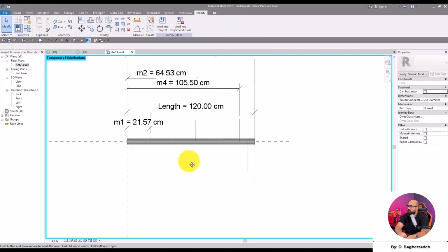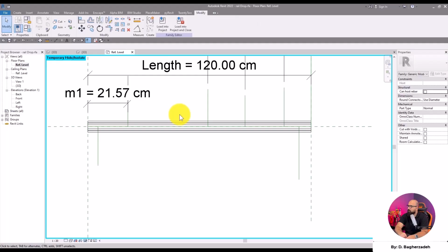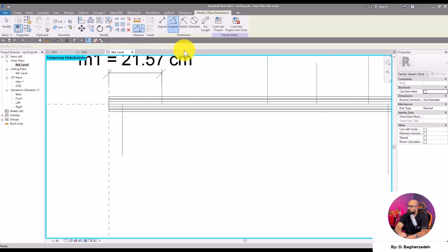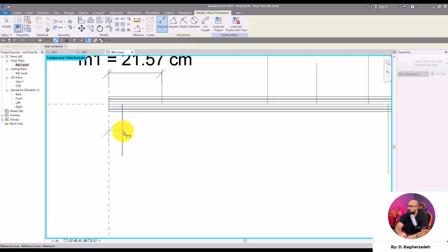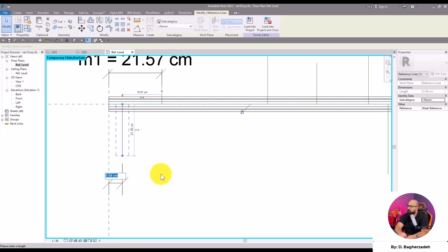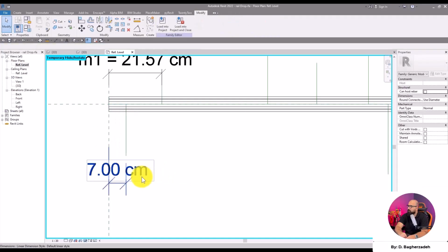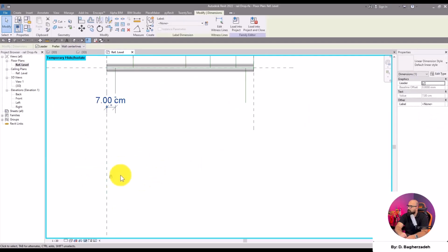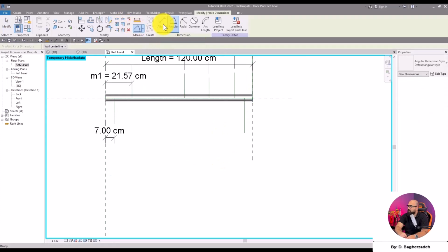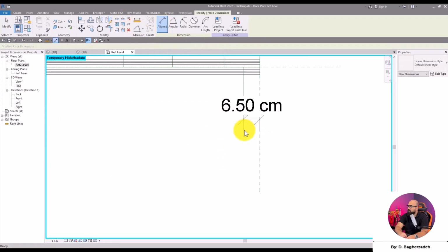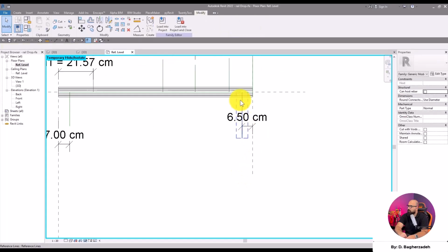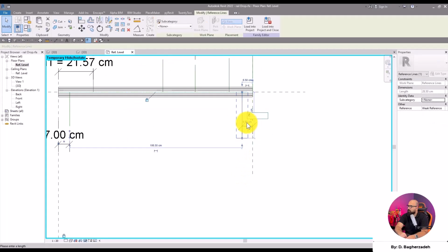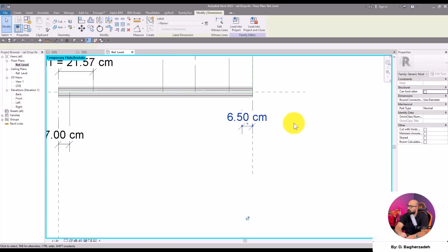Okay. Now guys, remember, the gap from the ceiling could or actually should change, but we need the same profile at the endpoints of our cable. More precisely, I'm going to go ahead and set a dimension here. Let's say 5 or even more, like 7 cm. Then let's lock it down. Okay, lock. Now let's do the same thing on the other side. Lock. Let me just set this on 7 cm first. What's happening?